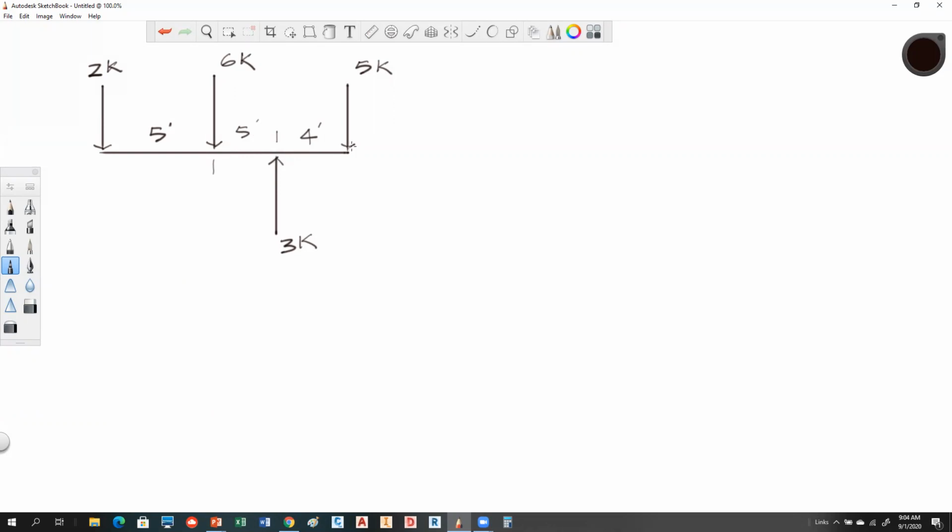Okay, so we want to get rid of all of these vectors and replace them with one vector that can be placed uniquely, and we have to know what its force is going to be, and what its location is going to be. So I've got to do 2 things I want to think about here. One is I need to know where I'm taking moments. So I'm going to just define my moments at the end of the beam. We're going to call that point A. The other thing is I'm going to say forces acting up and rotations acting clockwise are positive.